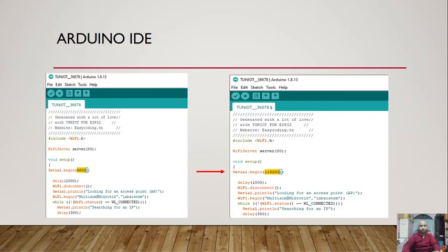Then after designing the block, we need to download it and run it using Arduino IDE. But first we need to adjust the baud rate value, changing it from 9600 to 115200, as can be seen in the picture with the yellow labeled section. Then click the compile and upload button. The compile button is to check whether there is an error in the program, and upload is to transfer the program to the ESP32.